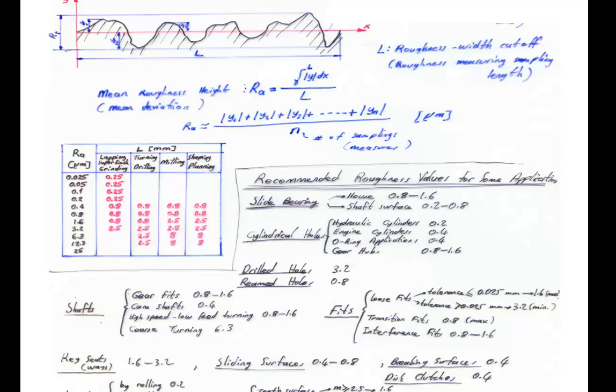Say that this is the first point at which the coordinate has been measured, at which the stylus just generated the signal. And this is the second point, this is the third point, this is the fourth, etc. Well, all the recorded values are taken to their absolute values. How? Relative to the level of the starting point, the measured value in the up or in the down direction. These are written and added.